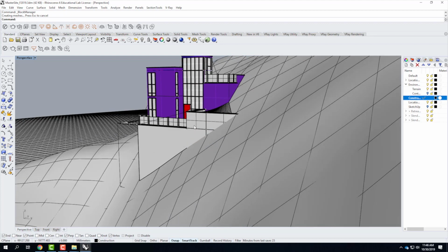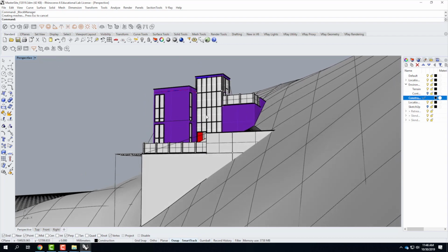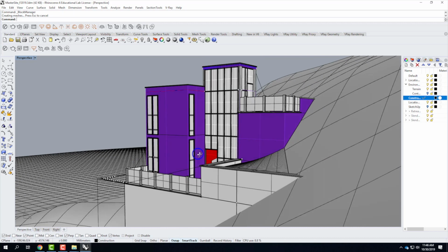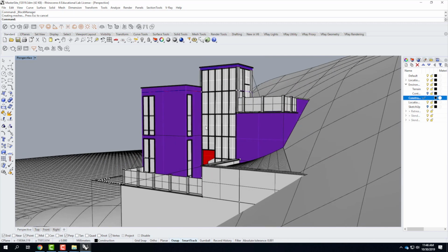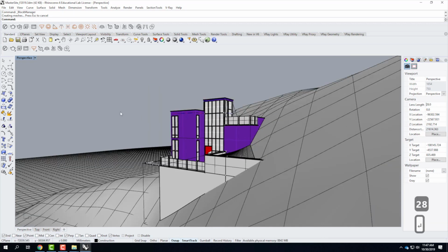The next piece of this is I need to figure out where I want to do my rendering of this particular building. So there's a kind of a nice view looking out this direction or so. So I can set up my view. The other thing that you can do is this view isn't a particularly wide-angle camera view. It's more of a telephoto camera view. With nothing selected, we'll cover this again when we get to the interiors, because that's when you definitely want a wider angle. With nothing selected, I can go to my Properties pane here, and I can change the lens length to be a little bit wider. So instead of doing a 50 millimeter, I could do like a 28. 28 is pretty good for an exterior shot. 18 is pretty good for an interior shot.